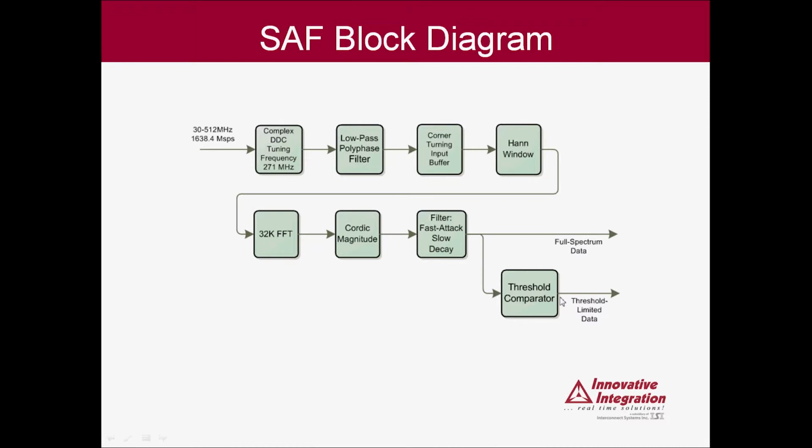In this mode, the user supplies bin thresholds for each of the 32K bins, and only bins exceeding their threshold are reported across the PCIe bus. The number of bins is limited to 512 in this operating mode.